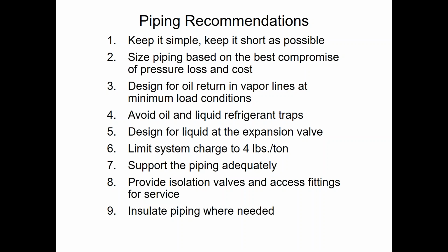Of course, piping supports, we'll talk about that. Isolation valves and fittings for service. And of course, insulate piping where needed, which is obviously on every inch of the suction piping, as well as any kind of fittings or valves. You should try to insulate those as well.